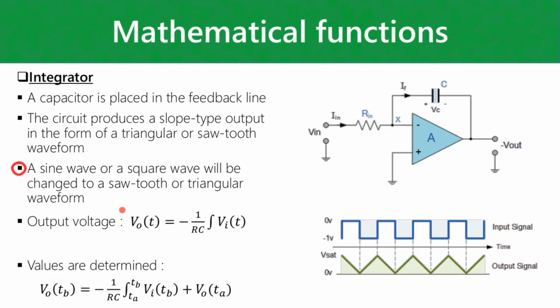It's not going to increase in frequency or anything like that. Anyways, so its general formula will look something like this. So it's 1 over RC, and then you take your input voltage and integrate it. Now there is a certain way we need to integrate, especially for this subject. So you need to be able to integrate a square waveform. But this is the example I actually want to get at, and then we can do this.